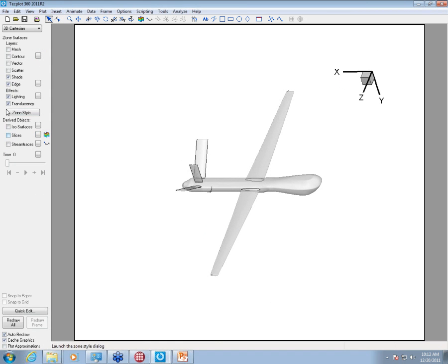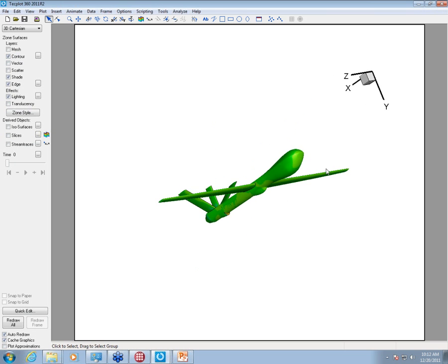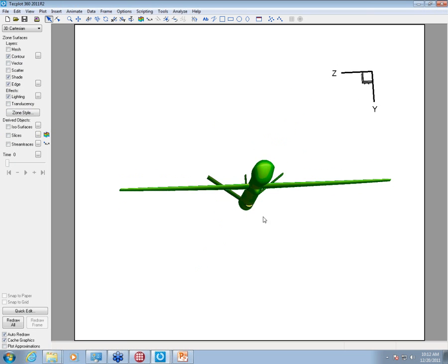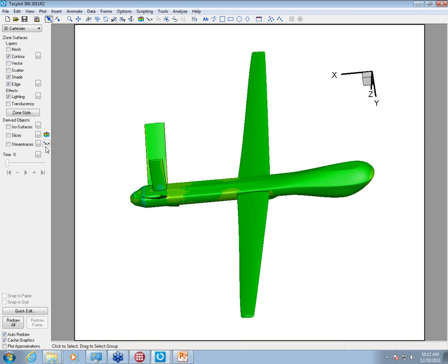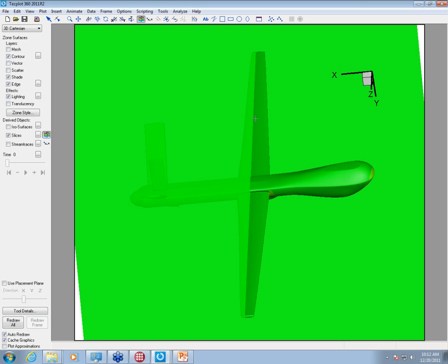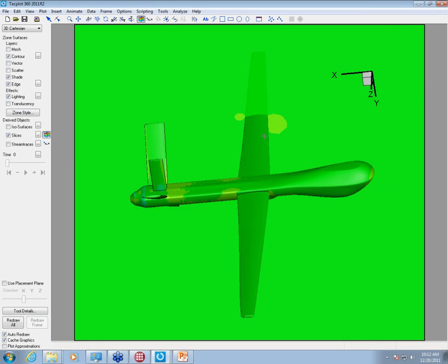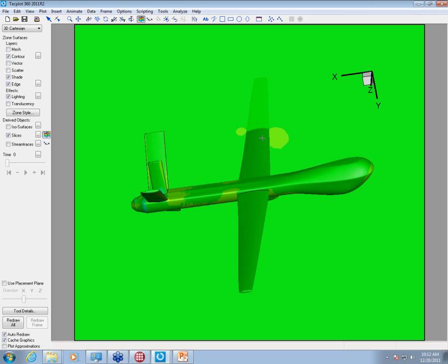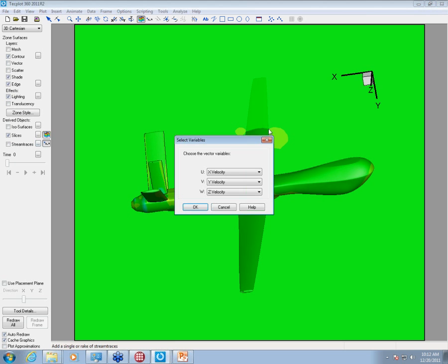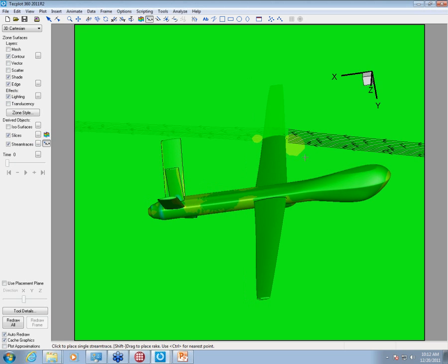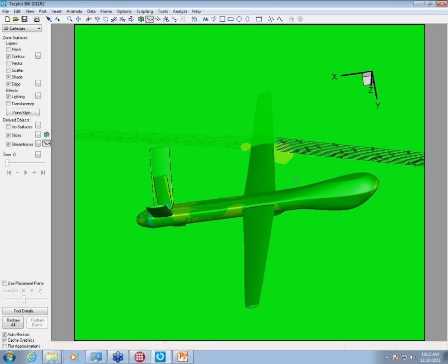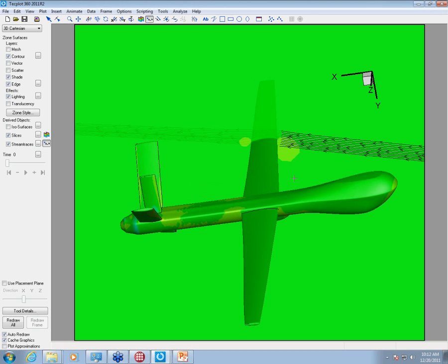We're going to just look at the surface pressures to start. And you can kind of get a sense. We can look at the basic leading edge, look at the trailing edge. We can maybe pop in a slice in the Z direction, which actually is perpendicular to the wing. And perhaps we'll look at a few stream traces just to understand the fluid dynamics around the wing. Now, this is not atypical of the way you might start your analysis when looking at a set of data.